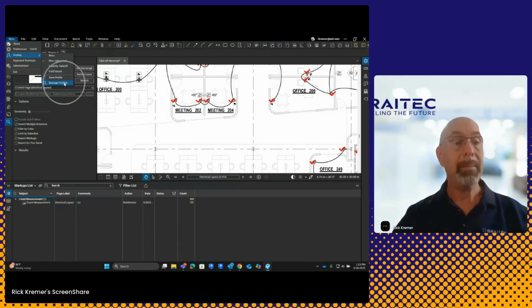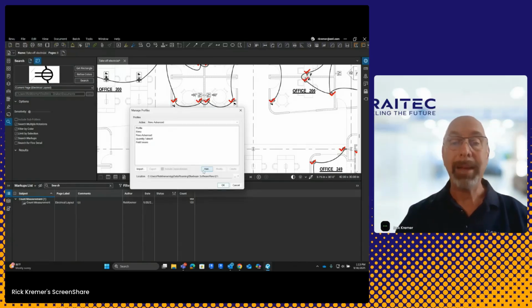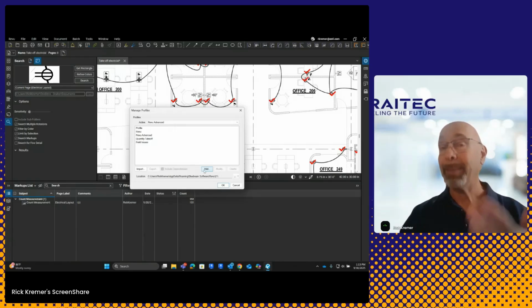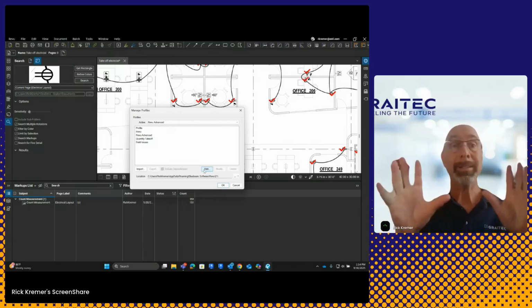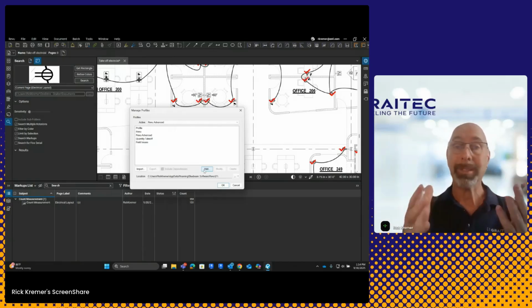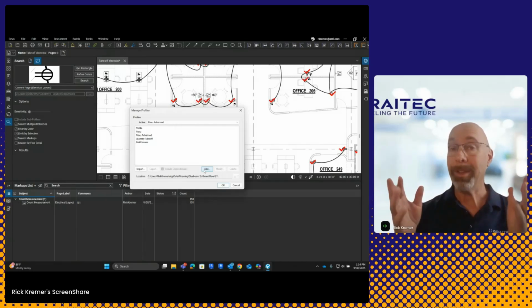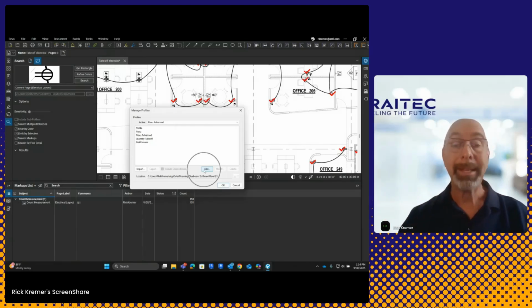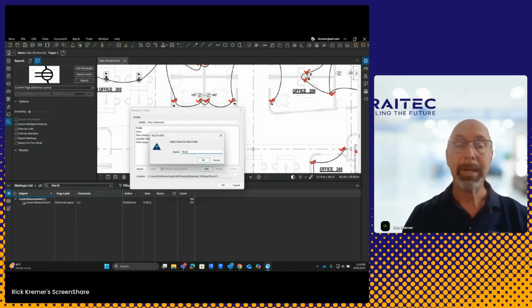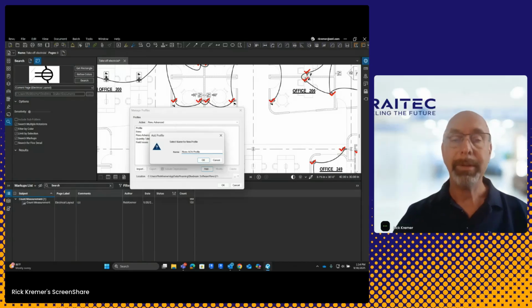Here, I'm going to click on Manage Profiles. In Manage Profiles, I'm simply going to go through and add my own profile. Again, this is all about standardizing the profile, which controls all of the icons and layout on your toolbars in Bluebeam Review. That way you can use this as a standard across the board. Here, I'll simply click on Add. I'll give it a name. I'm going to give this a name called Rick's ADV Profile. Pretty fancy, right? I'll go ahead and hit OK.